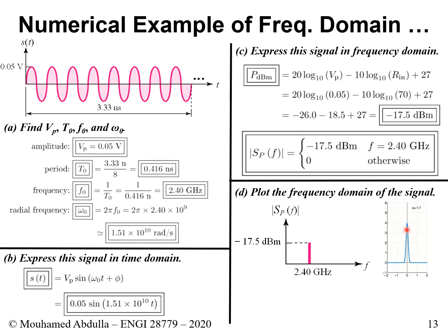So you might see some different shape of it, but it doesn't go all the way to infinity. It has a certain height. The height will be the value of the power, but it's not just one spike. It looks like a bell shape. Just be mindful that your spectrum analyzer will not necessarily show something very, very thin like this.